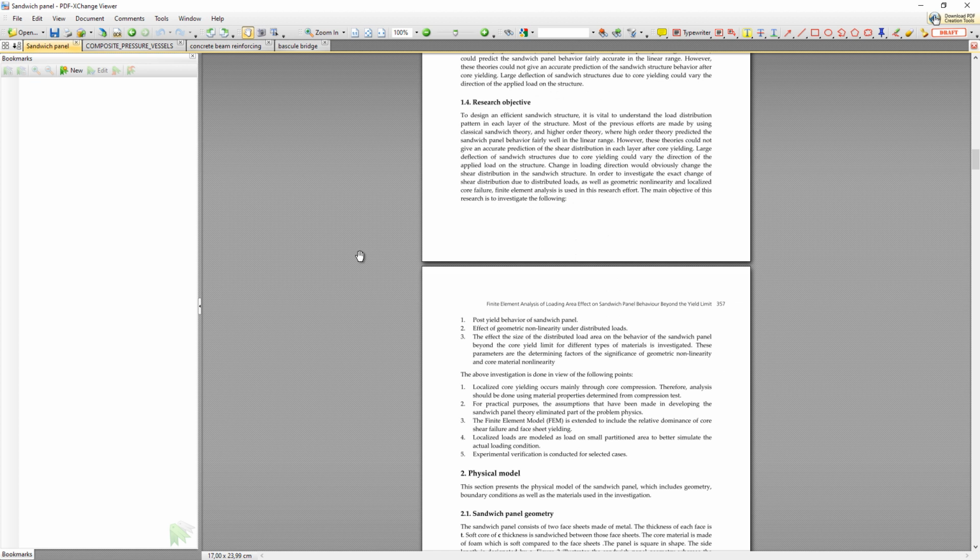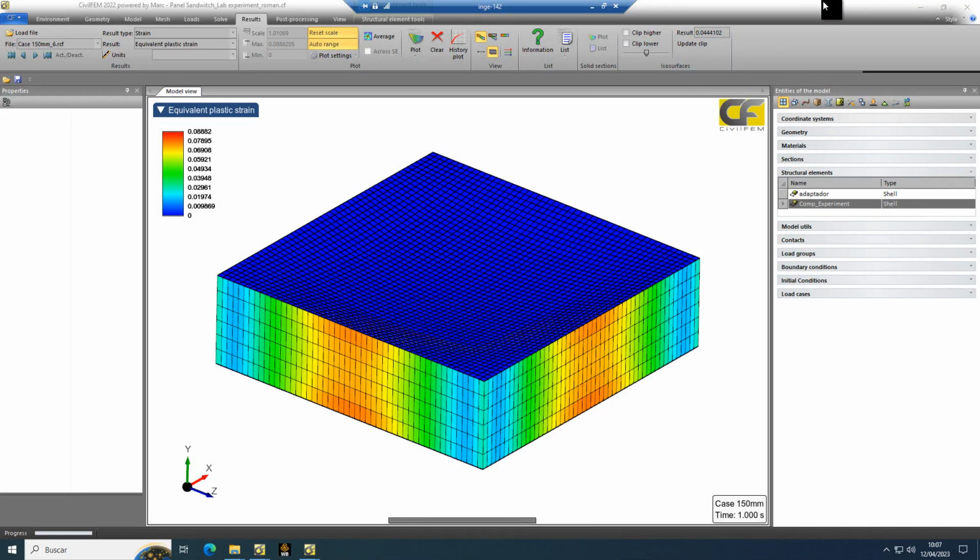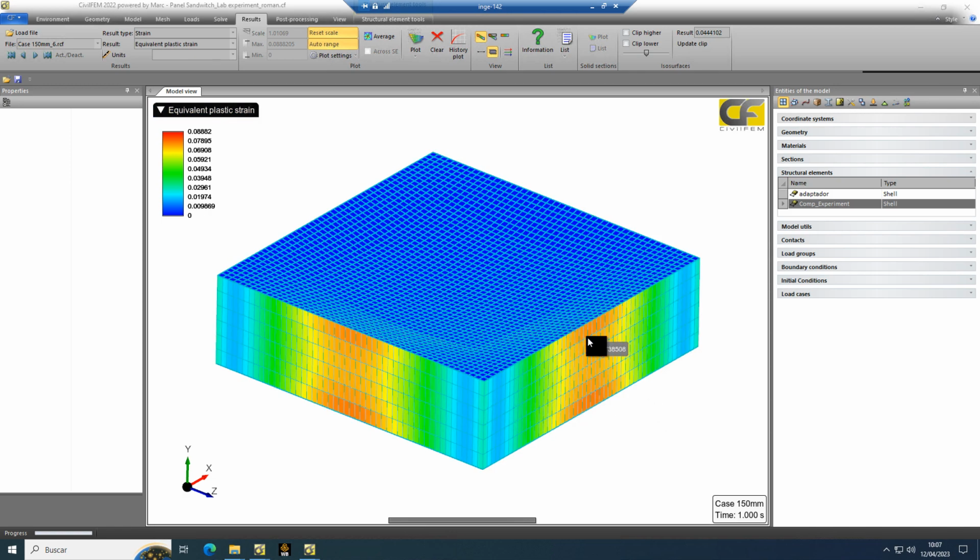Okay, so the model we are using is a nonlinear composite material model, which is generated with a shell element and with three different layers. There are two metal sheets that carry the bending moment. So the distance between those metal sheets due to the foam core increases the bending resistance. But the main problem of these models is the shear capacity that this foam can support. That is a very weak material.